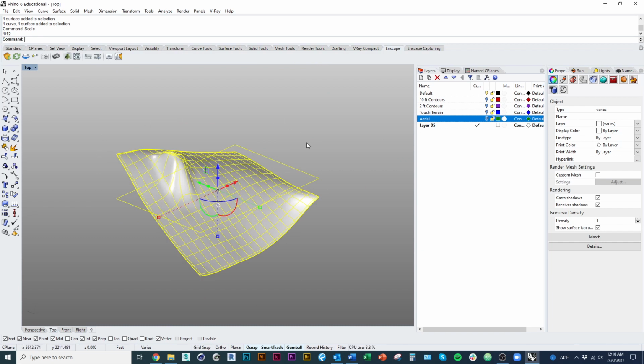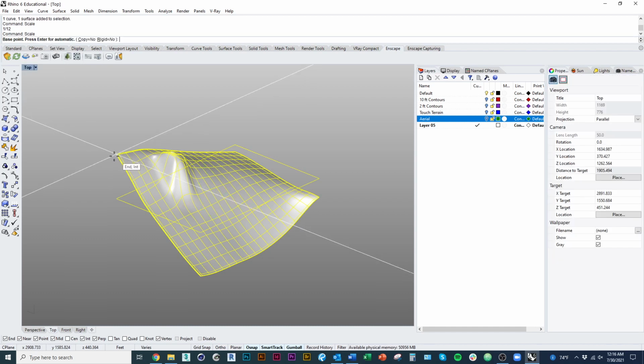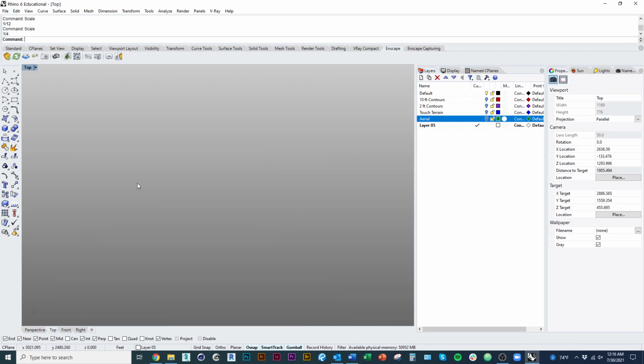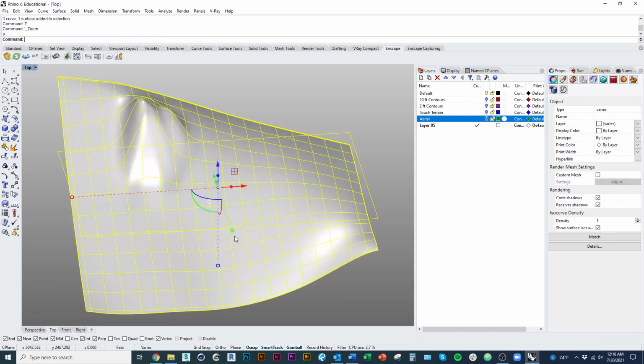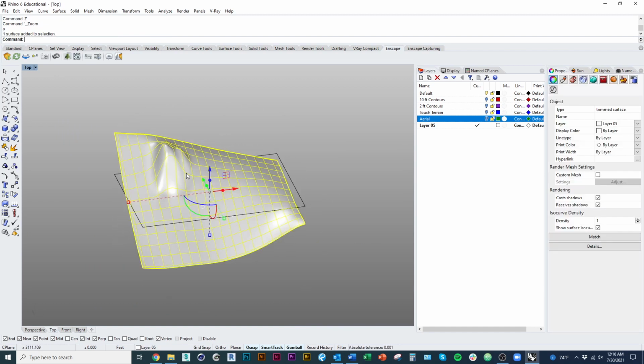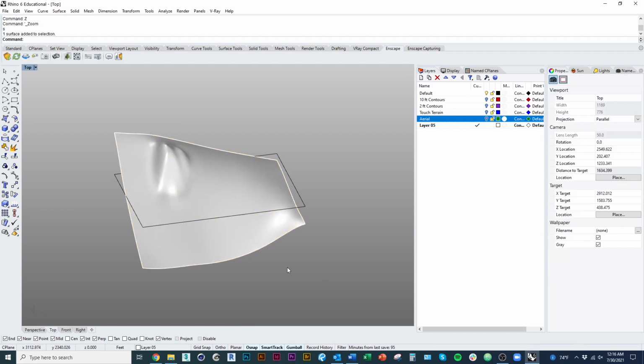So now it's essentially 1 inch equals a foot. Now I would scale it again to whatever my scale is. If I were doing a model at 1/8 of an inch equals a foot, I would scale it again by 1/8. Instead, I'm going to scale this to 1/4 inch. You can choose whatever scale makes sense for your model and the amount of area you want around your structure or whatever it is in your model. Okay, so that's 1/4 of an inch.